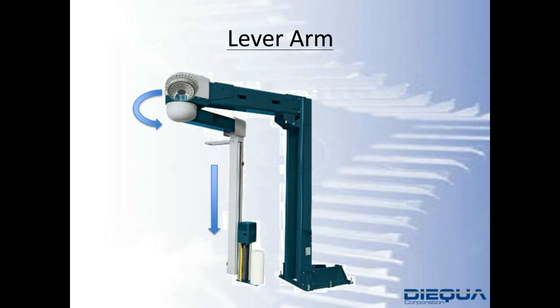And so the idea is by having a robot flange, or like I said earlier, a rotary output, you're able to bolt the horizontal lever arm directly onto the face of the reducer. The robot flange handles the axial load of the downward force. In this case, there's no radial load, but it's translated or interpreted in the form of a tilting capacity. So these are different applications, and how the application induces a reactionary element that the reducer interfacing with the rotary flange is asked to handle.